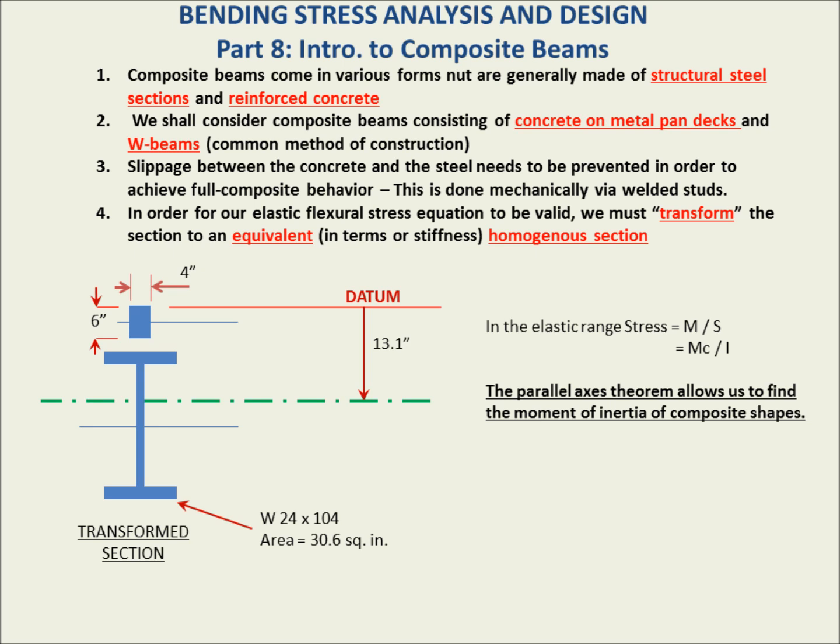When you have parallel axes, such as the ones we see here, that of the individual shapes shown as blue lines, and the neutral axis of the composite shape as the green dotted line, the parallel axis theorem can be deployed. However, the parallel axis theorem does not add anything new to the definition of the moment of inertia. It comes directly from the definition of the moment of inertia. It is simply a way of performing a calculation.